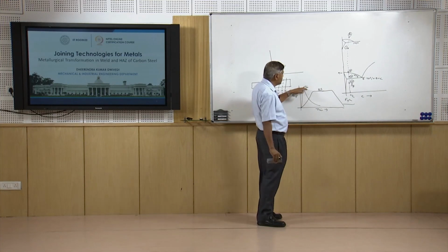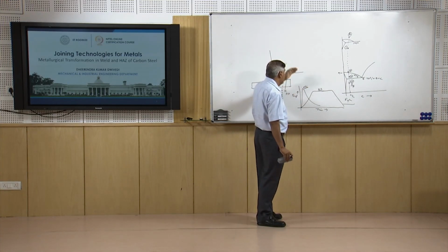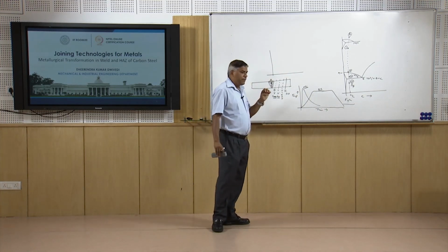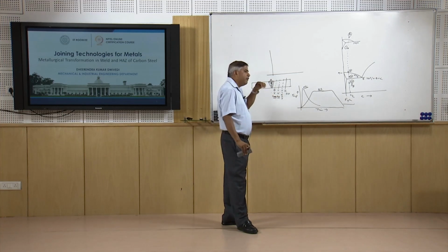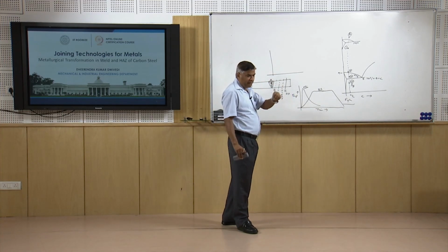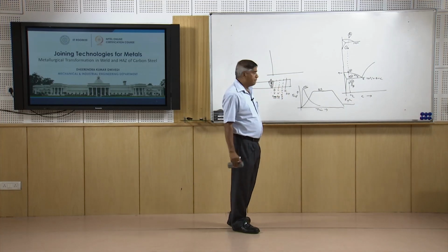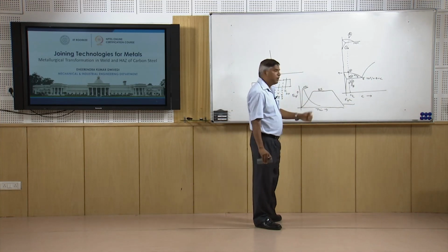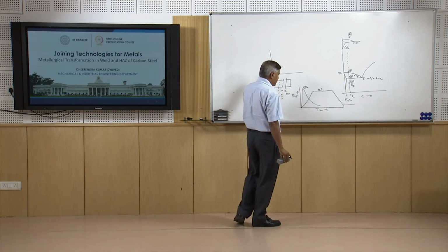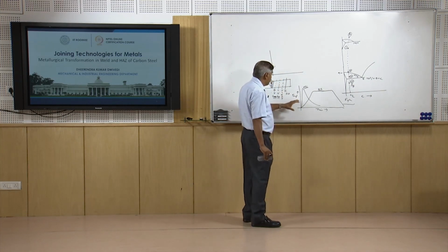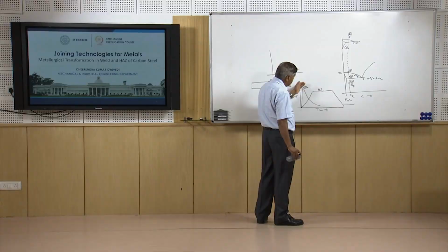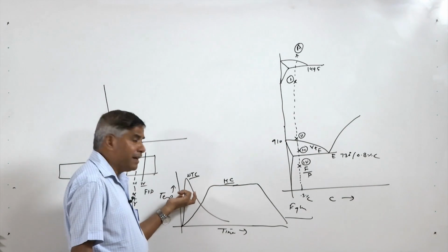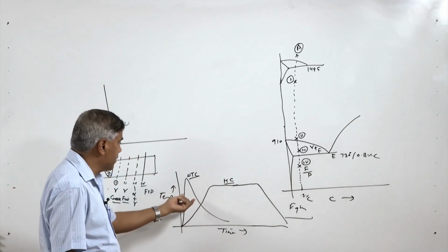So the temperature here reaches up even to the fusion temperature and above, but the heat treatment is carried out normally in the austenitic temperature band, which is say 50, 60 or 100 degrees centigrade above the upper critical temperature limit. So that is about 900, 950 or maximum 1000 degrees centigrade, not like 1400 or 1300 degrees centigrade. But the temperature experienced is much higher, and the rates of heating and cooling are much higher, but the time of retention at high temperature is limited in the case of the weld thermal cycle.